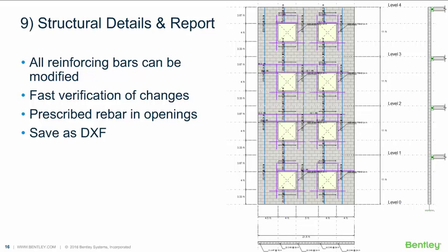One other quick one, type other mass. This is more on the structural system side, addressing it while I can here. Type other mass does get included in the seismic self-weight. And the other one is, can you model a masonry infill panel between the steel framing to take lateral loads only? It looks like that might have been in context to the RAM Structural System side of things. I think so. I'll think about that a little bit, and we'll answer maybe towards the end since it's a little more involved. Okay. Sorry to disturb you. Perfect.